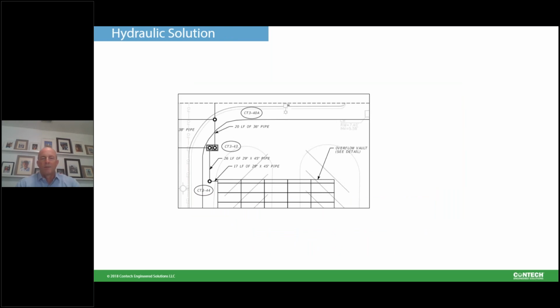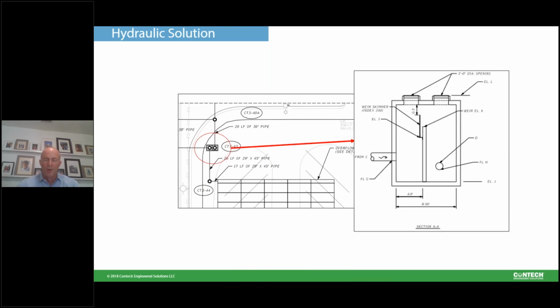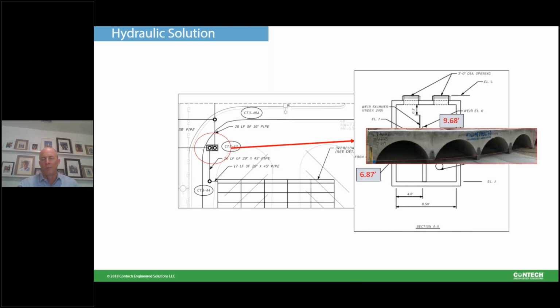A second design challenge we had to overcome was the hydraulics of the overall design in the storage system. We typically in Florida on the coast especially have a very narrow vertical profile to work with, but in addition to that, on this project at a port, we had limited ability to control the finished grade elevations and therefore the hydraulic controls. So we had to take the engineer's drainage system design and hydraulic control design and ensure that we could adapt a concrete solution, since that was what was preferred by the port, into those elevations, which we were able to do.